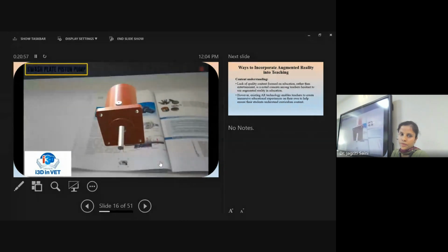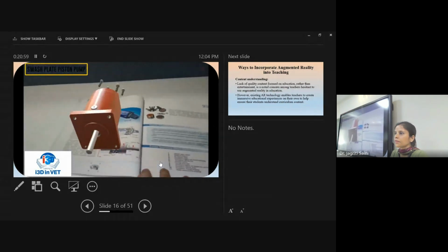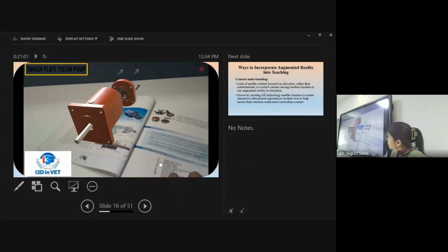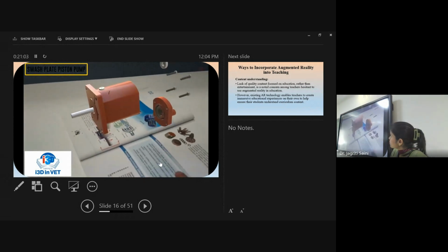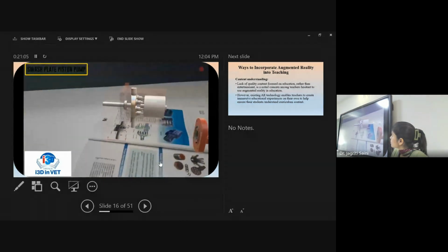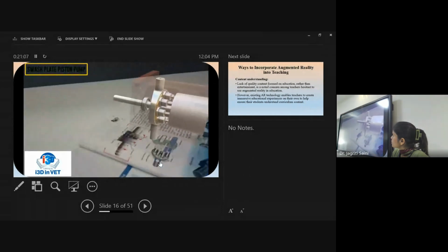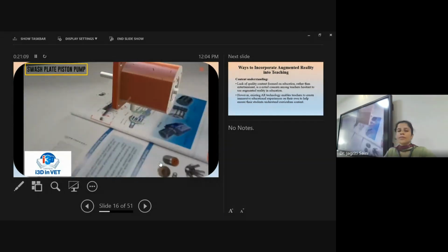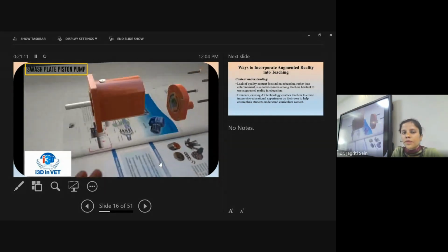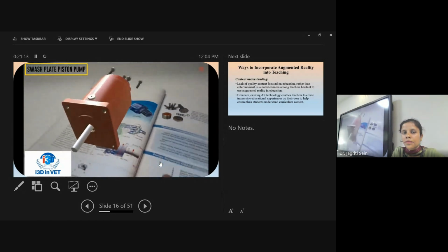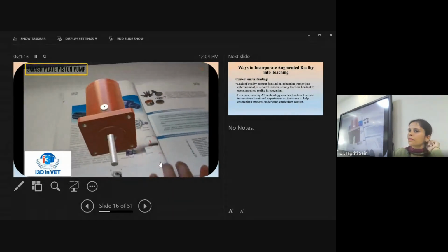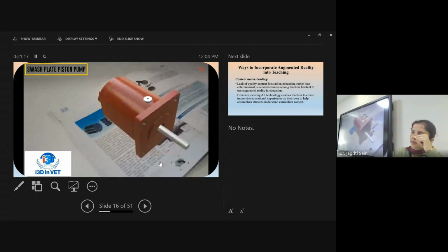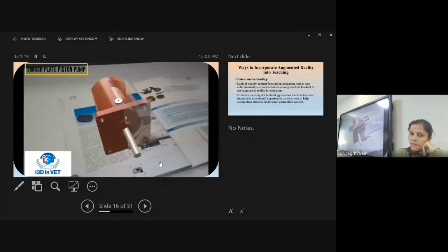Piston pumps come in many different forms. A swash plate is a device used to translate the motion of a rotating shaft into the reciprocating motion of a piston. Swash plate piston pumps have a rotating shaft connected to a cylinder block containing pistons, which are pressed against the stationary swash plate that sits at an angle to the cylinder.